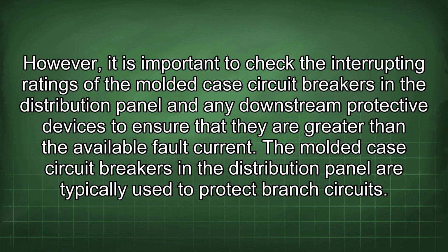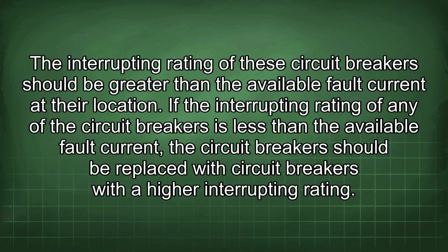The molded case circuit breakers in the distribution panel are typically used to protect branch circuits. The interrupting rating of these circuit breakers should be greater than the available fault current at their location. If the interrupting rating of any of the circuit breakers is less than the available fault current, the circuit breaker should be replaced with circuit breakers with a higher interrupting rating.